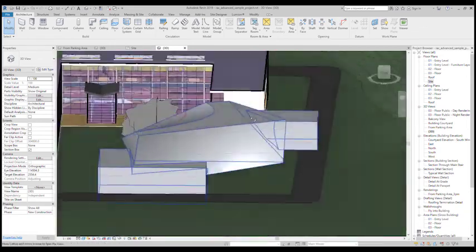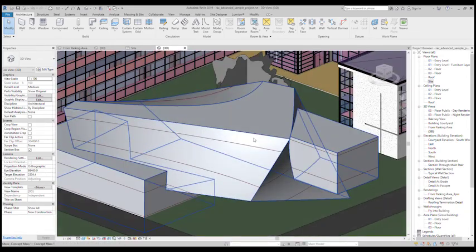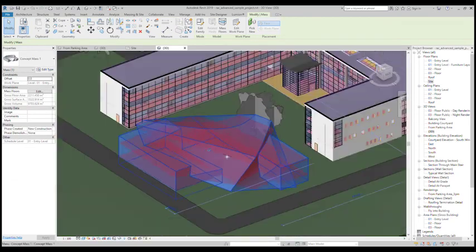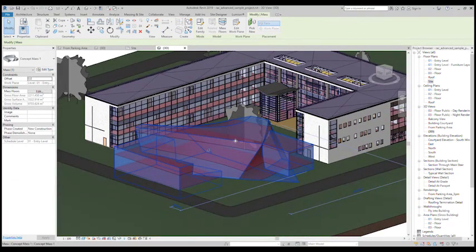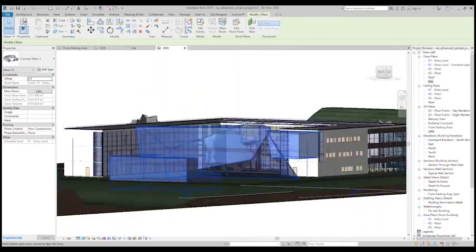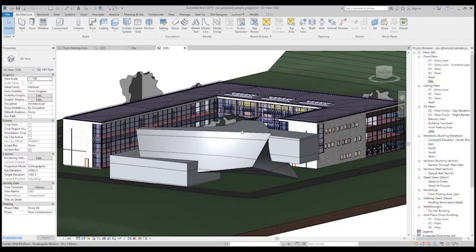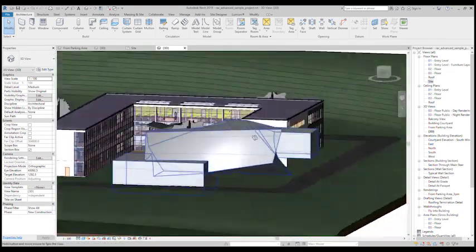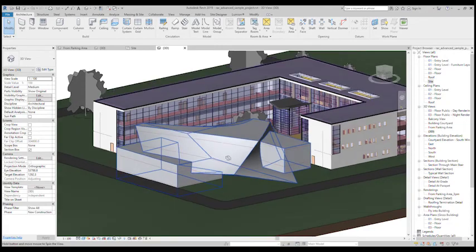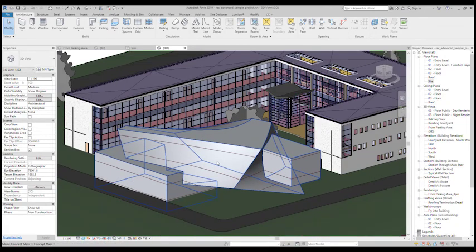We are going to allow Revit to do that automatically to our mass, and this is called the conceptual mass by face method of doing your modeling. Now, again, like last week, I know we've actually been through all of this with most students, but it's good for us to go through this again, because this is the most important part of your entire process of taking your conceptual volumes, which you've explored and done some crazy or creative stuff in, and then making them real.